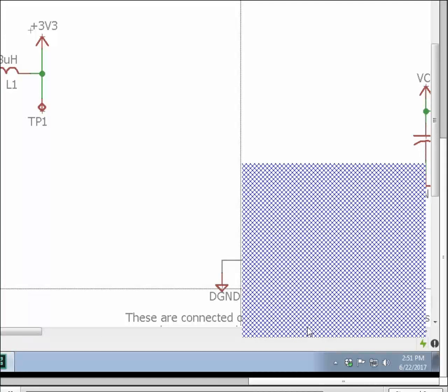No, Mike, no, because the components will be on the surface layers. You can use interlayer routes as part of a design block, but the components will still be on top and bottom. So you have the traces on the inner layer that will come through, but not the components itself.